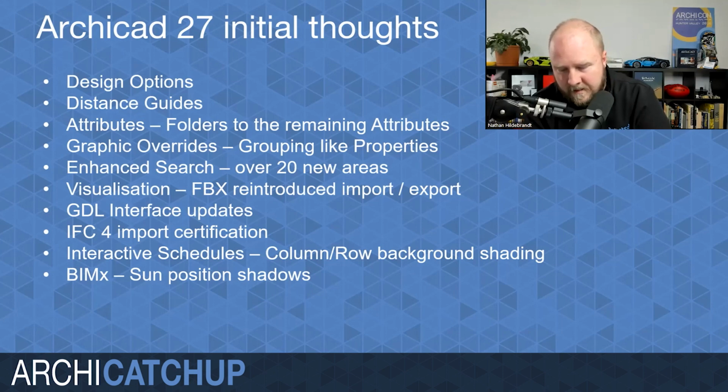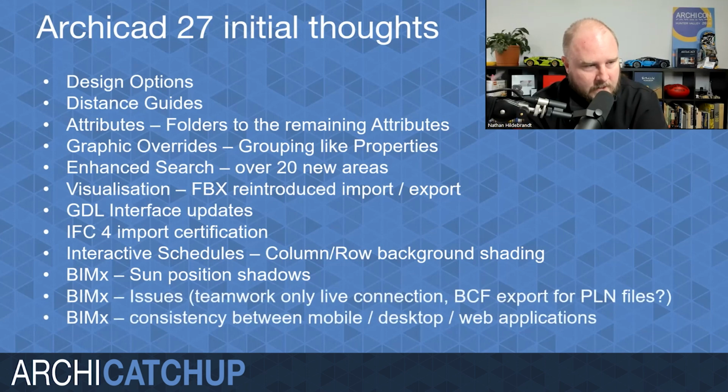It's really good to be able to see, and for your clients as well, where the sun is going to hit on their houses or buildings when it's in use at certain times of the day. The key thing to getting this to work properly is making sure you have the correct geolocation in place for your project. So make sure you do that in your project settings, that you've got the right latitude and longitude in place. Otherwise your sun will be inaccurate.